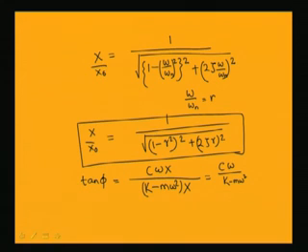From this equation you can see that when r equals 0, that is when omega equals 0, this becomes 1 and this part equals 0, so it is 1 by 1. So, this becomes 1. For an undamped system, that is a system without damping, zeta equals 0, and this becomes 1 by root over 1 minus r square whole square.